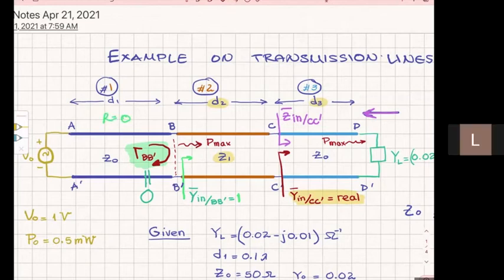All right. So you will have reflection coefficients at BB prime, CC prime, and another reflection, so different VSWRs at CC prime, DD prime, but the final result at AA prime, BB prime is going to be the reflection to be 0. So okay, a VSWR of 1. That makes sense. Yeah.